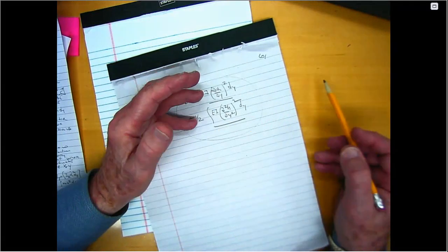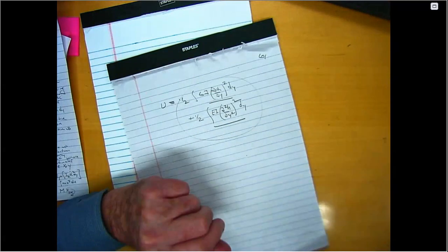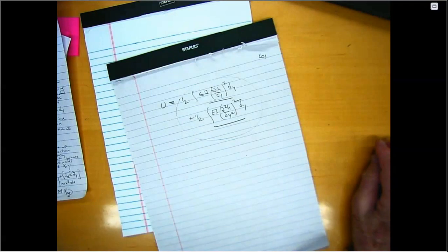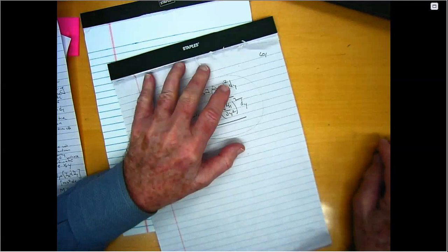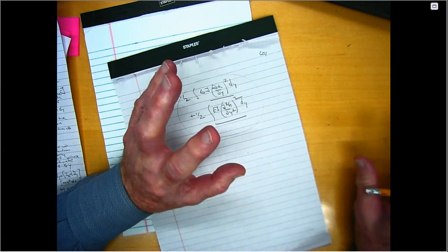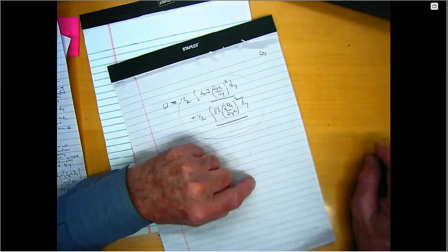Now, if I had chosen as my axis system the center of gravity, there is a center of gravity axis that moves along the thing. Then there would have been no coupling in the kinetic energy terms, but now there would be coupling here. And because these expressions are usually more complicated, you usually say, I'll pay the price of increasing the complexity of my kinetic energy expression to save myself some effort when I write down potential.